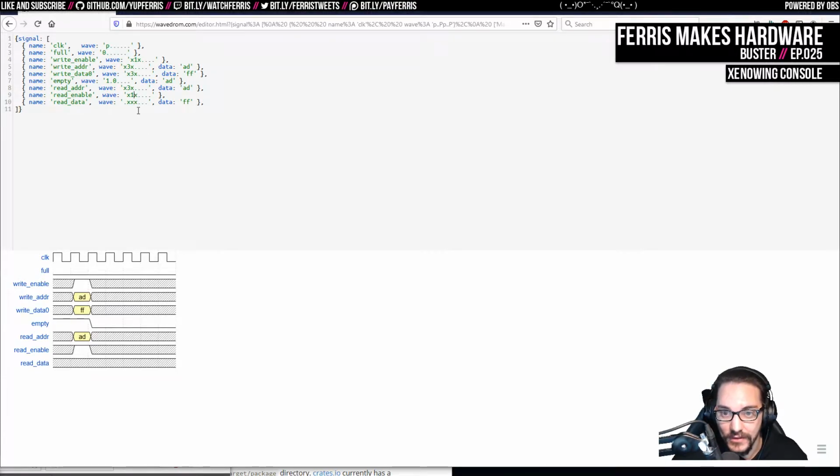And so we actually need to hold these signals for another cycle, until we get a cycle where we're asserting it and the FIFO was not empty. As soon as that happens, on the following cycle the read takes. Right? I think this generally makes sense.